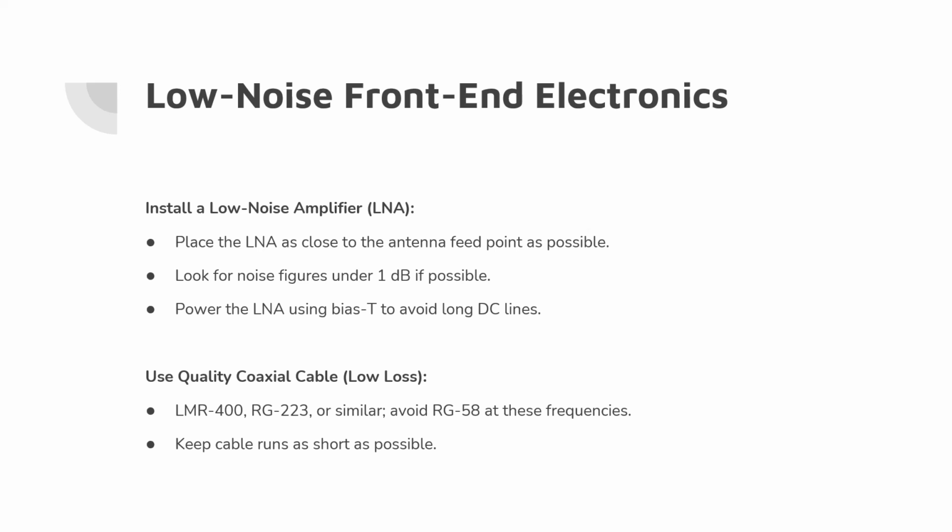And that was a special cable, so it actually has two RG6 cables in there, because one was for the S band and the other was for the Ku band reception, and then it has lines for the power for the motor, and also lines for the polarization. The LNB for satellites has an interesting construction on the feed. It's a dipole.